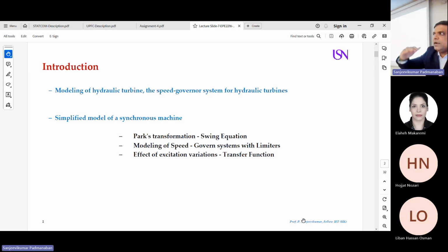When you reach the rated excitation, you get the rated voltage. If you are not giving excitation, what happens? The synchronous machine will generate some voltage, but very minimal. It will not reach the rated value. So excitation is nothing but increasing the magnetic field, the electromagnetic field. The electromagnetic field is directly proportional to the output voltage. I don't go very deep into the dynamics.